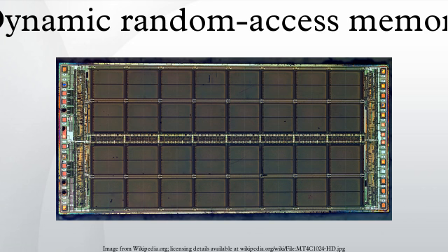DRAM modules: single inline pin package, single inline memory module, dual inline memory module, Rambus inline memory module, technically DIMMs but called RIMMs due to their proprietary slot. Small outline DIMM, about half the size of regular DIMMs, are mostly used in notebooks, small footprint PCs, upgradable office printers and networking hardware like routers.